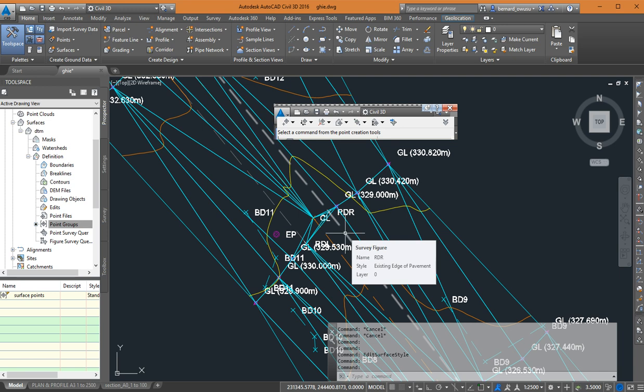You remember that we created a point group by name, a surface point or whatever, and that is the one that we are using to build our surface. So if yours is connecting every point, then you have to delete and redo.